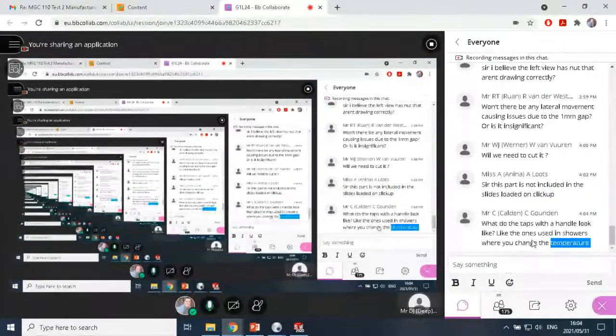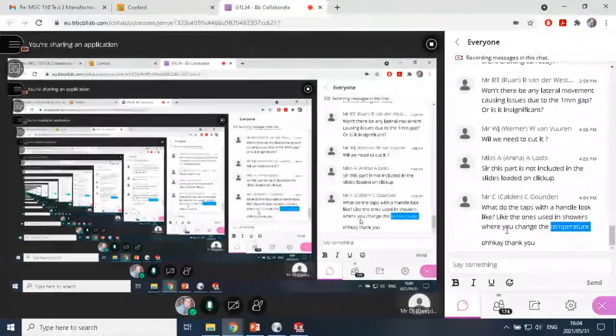So those taps are basically a variation on the ball valve, just with a more complicated ball mechanism on the inside. Maybe go check it out on the internet, as it's not super relevant for this lecture now, but it's basically got two ball valves next to each other, one for cold, one for hot. And as you move the handle, I think it's called a mixer tap. So as you move the handle, it changes the size of opening that each of the ball valves lines up with, and then that will change the amount of hot or cold water that flows through the tap.